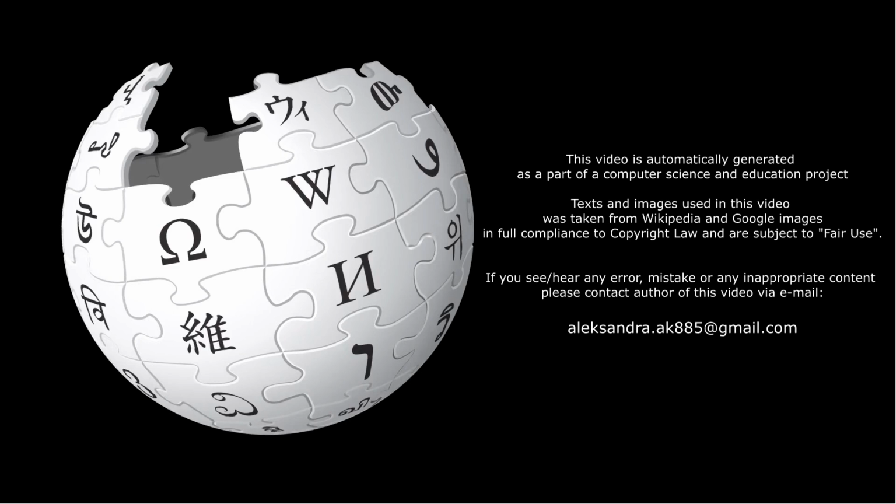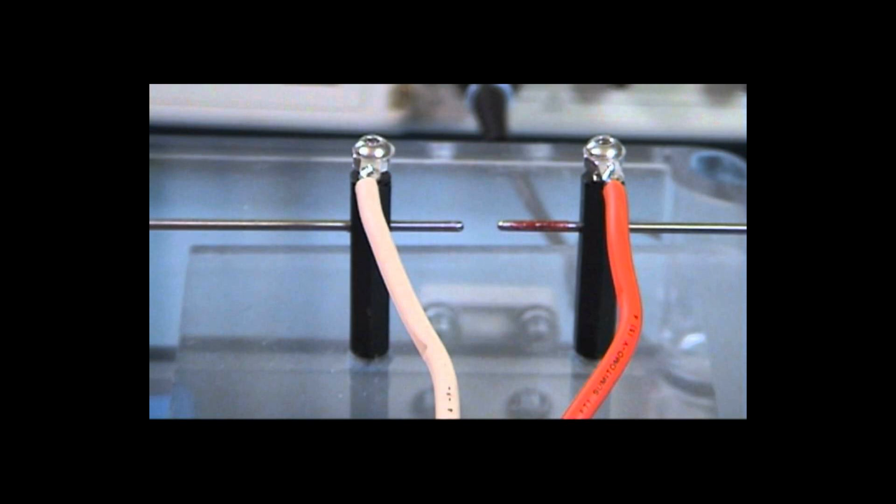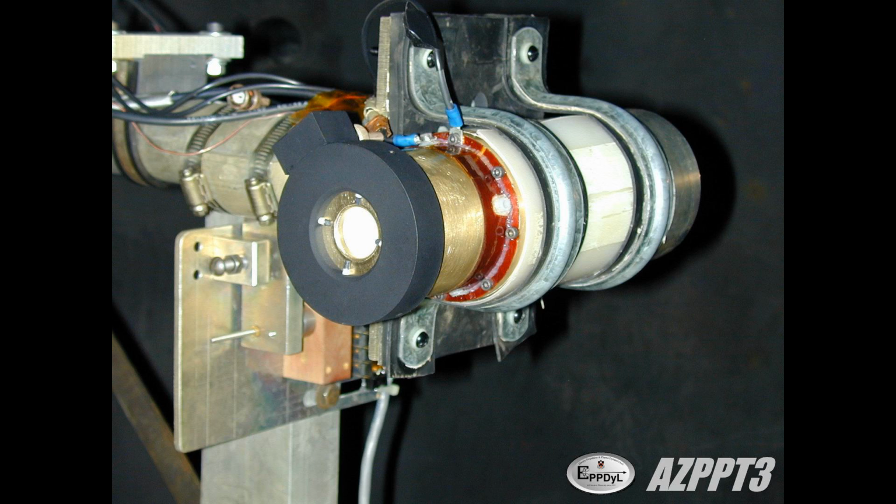It is therefore advantageous to use an electric propulsion system such as a PPT to generate high interplanetary speeds in the range 20 to 70 km per second. NASA's research PPT, flown in 2000, achieved an exhaust velocity of 13,700 meters per second, generated a thrust of 860 micronewtons, and consumed 70 W of electrical power.